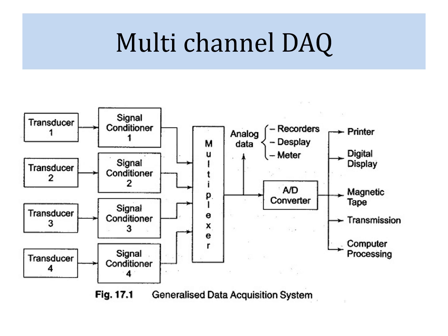However, in multi-channel DAC we can handle multiple signals in parallel, because for that we have multiple A to Ds and other filters all embedded into the signal conditioner. So whenever we have multiple signal conditioners, and that too of different ranges, as we have seen in MyDAC, some of the A to Ds are, let's say, 8-bit, some of them are 10-bit, some signal conditioning works from 0 to 5 volt, some at, let's say, 0 to 12 volt. So there are different signal conditioning.